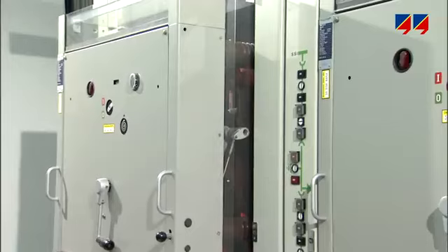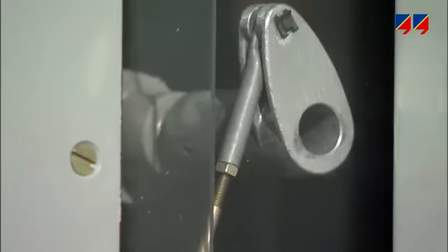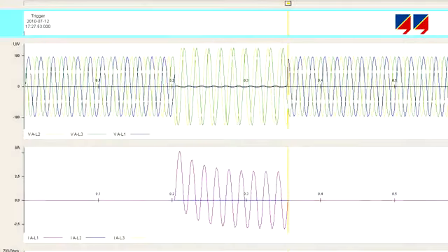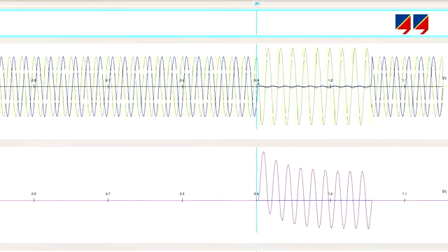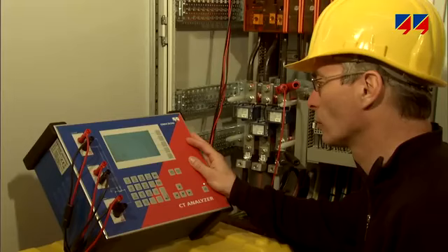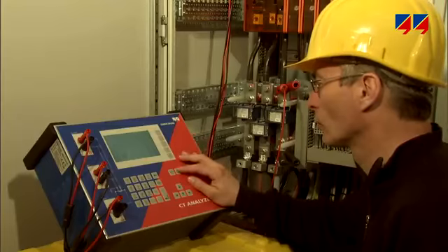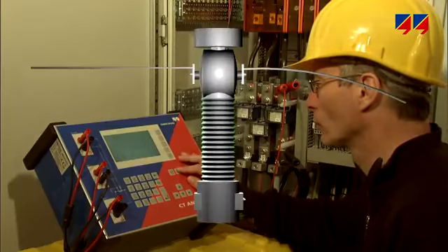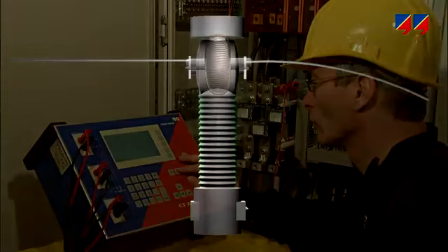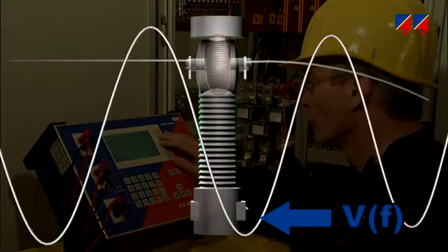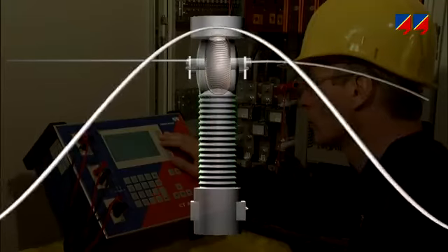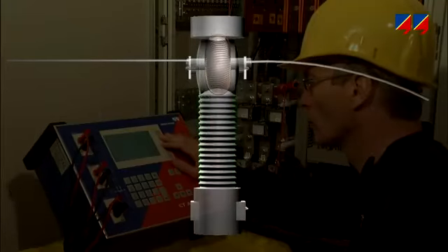Additionally, many of the parameters characterizing a CT's transient behavior, for instance during auto-reclosure cycles, such as secondary time constants or remnants, cannot be determined with classical test benches. CT Analyzer allows the limitations of the various traditional methods to be overcome. It opens the black box through secondary injection with variable frequency and a patented low-voltage, low-frequency method for excitation measurement.